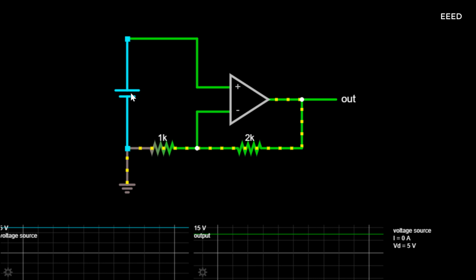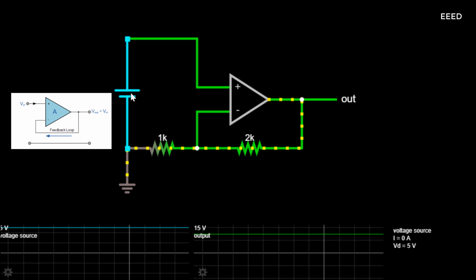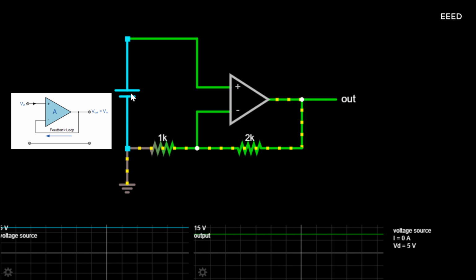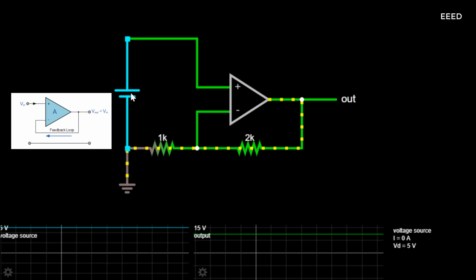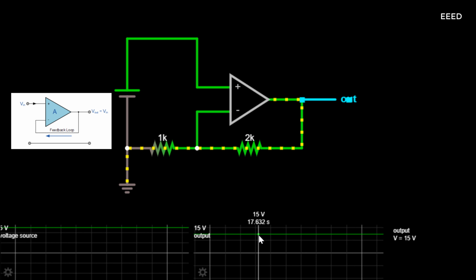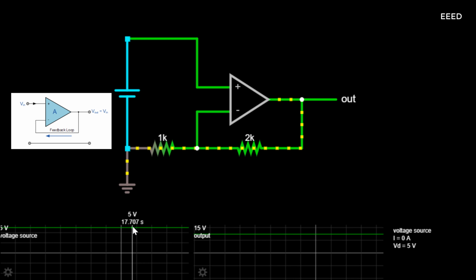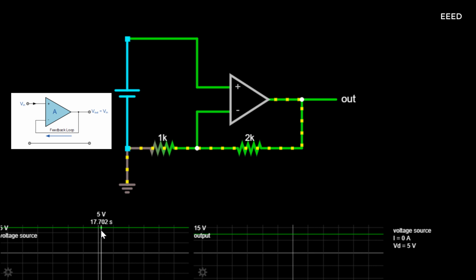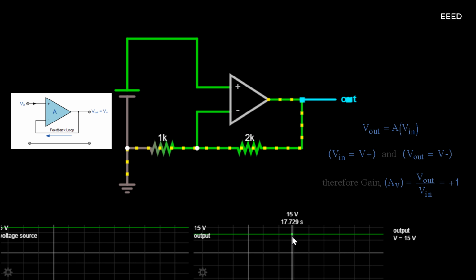Non-inverting voltage follower. In this non-inverting circuit configuration, the input impedance RIN has increased to infinity and the feedback impedance RF reduced to 0. The output is connected directly back to the negative inverting input, so the feedback is 100% and VIN is exactly equal to VOUT, giving it a fixed gain of 1, or unity. As the input voltage VIN is applied to the non-inverting input, the gain of the amplifier is given as: